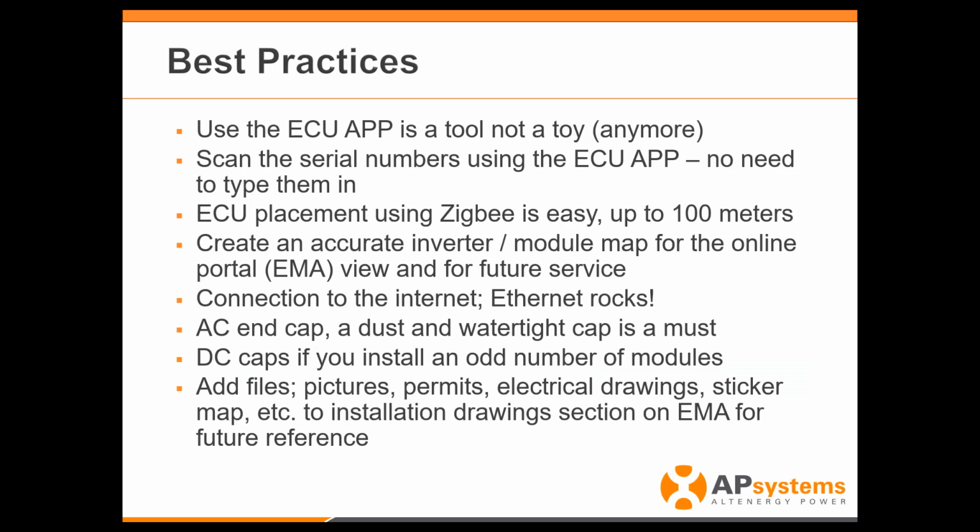Okay, so let's just do a little bit of review. So in review, the ECU app is a tool, not a toy. And like I said, I can't emphasize enough. When you get on site, it's tempting, and I've done it myself, right? That's how we used to install solar. At the end of the day, we grab that ECU and say, okay, where's that ECU? What I want you to do when you get on site now is get that ECU out of the box and plug it in when you get there.